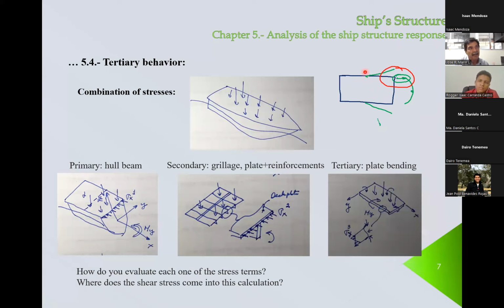In this area, how much is the shear stress, Mr. Carranza? 0. In this area, the shear stress is important, but here it is 0. So that's why in this area, we usually include a little bit more thickness than in this area. In both, the normal stress is very high, but on the side, not only is the normal stress very high, but also the shear stress is important.